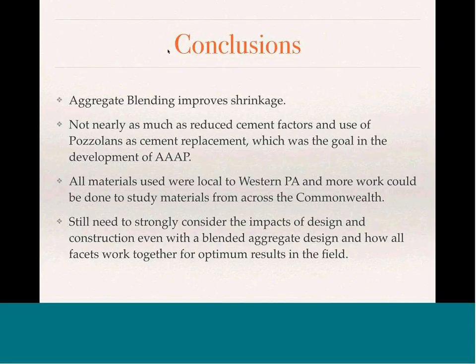So, you know, we're light years ahead of where we were 10 years ago with bridge deck concrete, and we're looking at ways to improve it from there. But again, the big jump was to get the total cementitious down and utilize the percentage of pozzolan. Materials in this study were local to Western PA. Some more work could be done with materials from across states, and that's an important component.